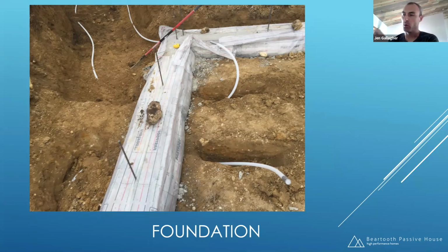Whenever the white box senses that the temperature from the outside air is cold and it could be warmed up, it kicks that circulation pump on, and that circulation pump then circulates glycol through these tubes, and we just use the heat of the ground, probably 45 or 50 degrees, to heat up the incoming air. So that was something that, you know,